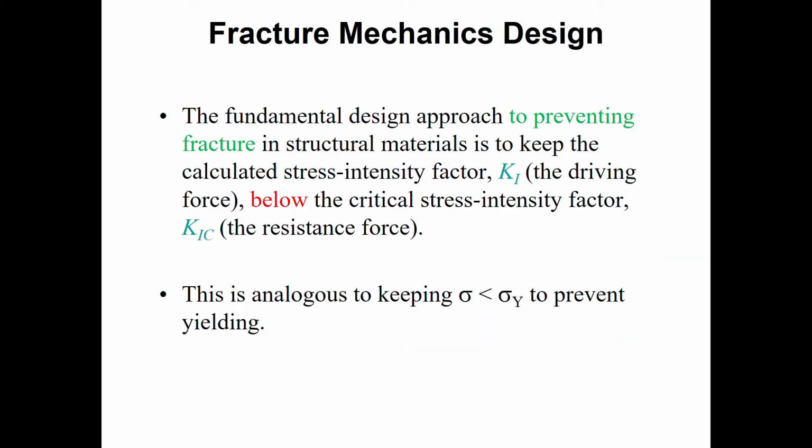Fracture mechanics design: the fundamental design approach to preventing fracture in structural materials is to keep the calculated stress intensity factor K1, the driving force, below the critical stress intensity factor K1C, which we consider as the resistance force. This is analogous to keeping sigma less than sigma yield to prevent yielding.